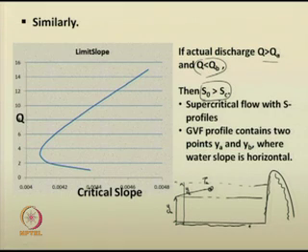There the water surface profile will be horizontal, then it will make a jump and will have an S1 profile. So, it will be having S3 and S1 curves, right.